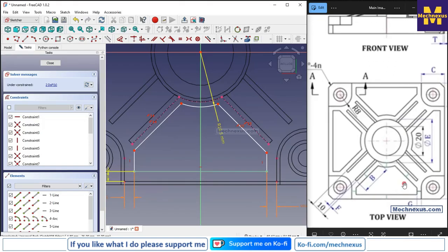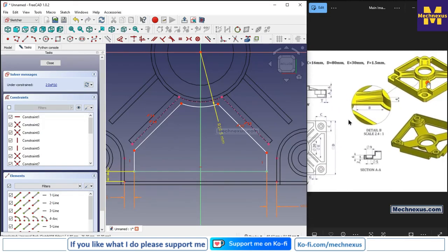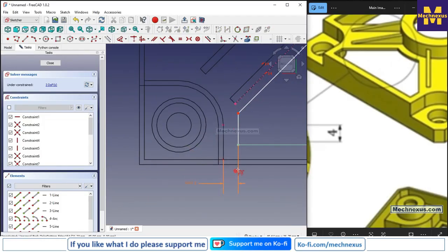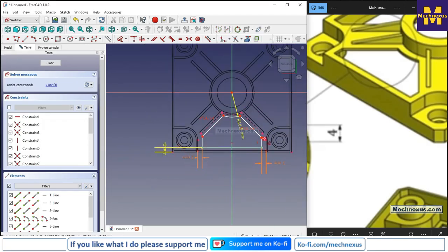So here if you see, so we will give it a 3 mm from the outer edge. So for this we will select a smart dimension, select this point and this point and make it 3.